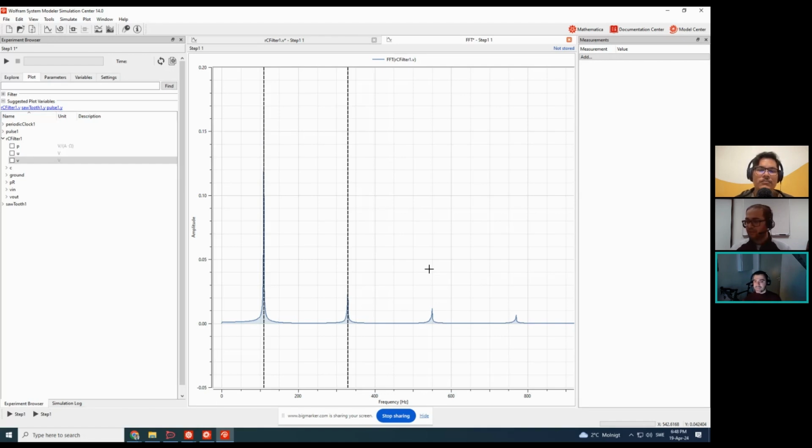Right. So let's say you have a motor that is operating, and you get the frequency measurements from the motor's outer body, and then you have a model of it in System Modeler. You could simulate and then try to compare the frequency response of what you got versus what your model tells you, and then perhaps you can use it to troubleshoot.